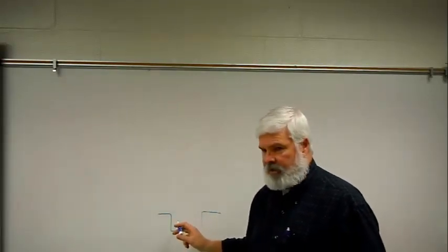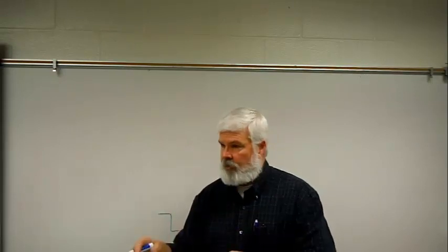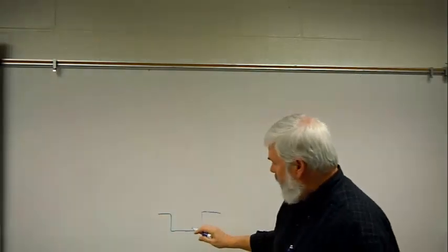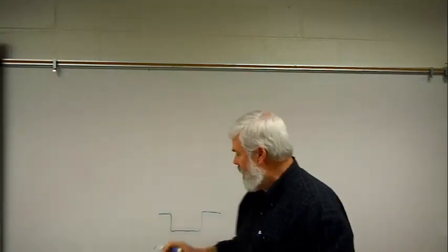This is the footing, and what goes into the footing on a residential structure depends upon where in the country it's built. If it's the kind of sandy soils that they have in Texas, it's going to be different requirements for the footing as it is with the Georgia red clay that we build on here. The red clay is a really good dirt to build in. It doesn't shift. It compacts extremely well. I mean, clay compacts almost as hard as concrete. So our typical footings may only be 16 or 18 inches wide. That's something you have to look up in a code book to be sure.